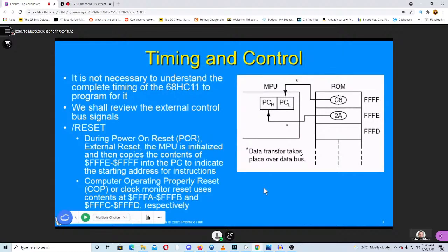No, brownouts. Those are concerning. So it's good now, they have power supervisory circuits that will detect that. You have to buy them, of course, if you're building a system where it will detect brownouts and formally issue a reset if it does detect it, or wait till the brownout passes. But these are certainly things that you have to be aware of.